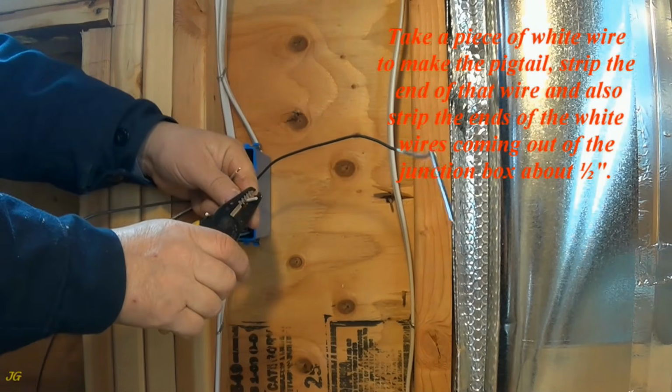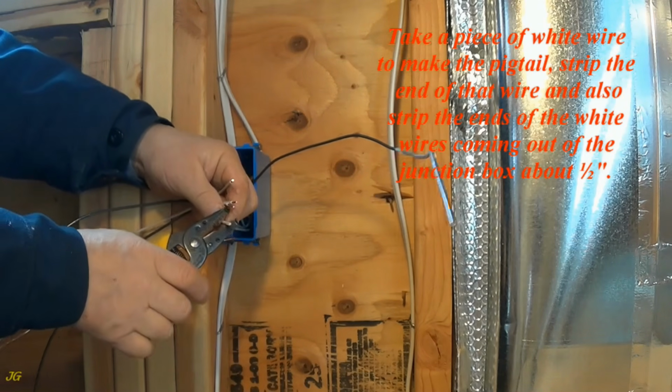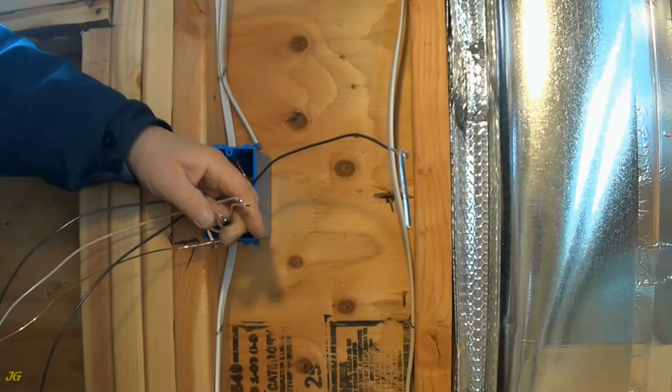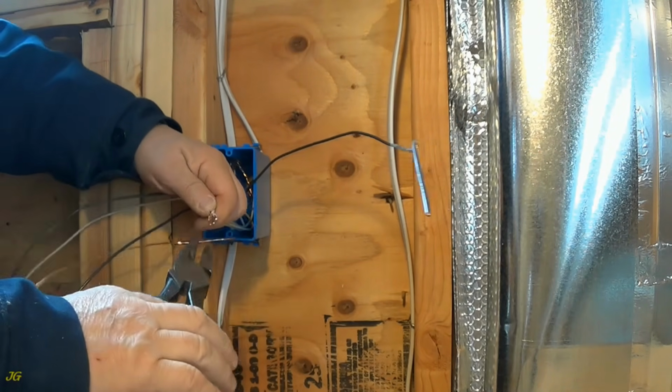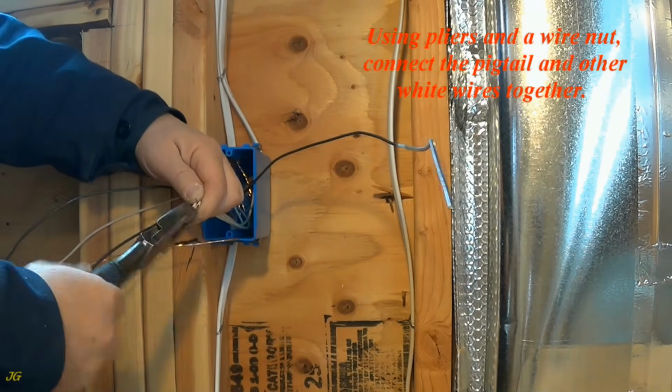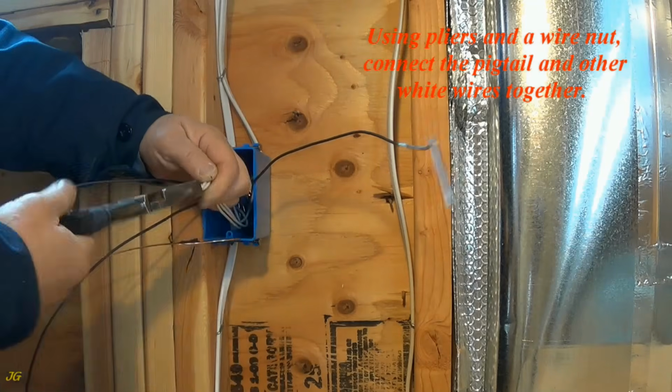Strip the end of that wire and also strip the ends of the white wires coming out of the junction box about 1/2 inch. Using pliers and a wire nut, connect the pigtail and other white wires together.